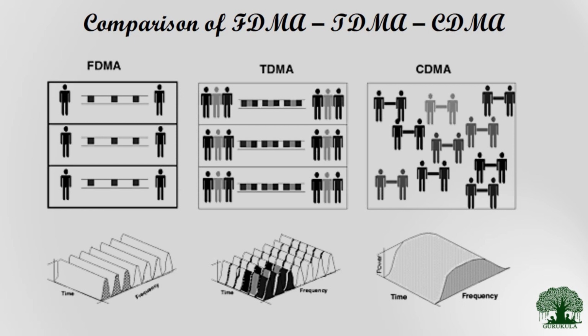So in order to overcome these two drawbacks of FDMA and TDMA, we have introduced the CDMA technique, where each and every user will be allotted a different code, so that literally there will not be any restrictions on the frequency and as well as the time, so each and every user can send their data by utilizing the entire frequency spectrum and for the entire period of time. So this enables all the users in the system to communicate simultaneously, and they can achieve high data rates as compared to FDMA and TDMA systems.